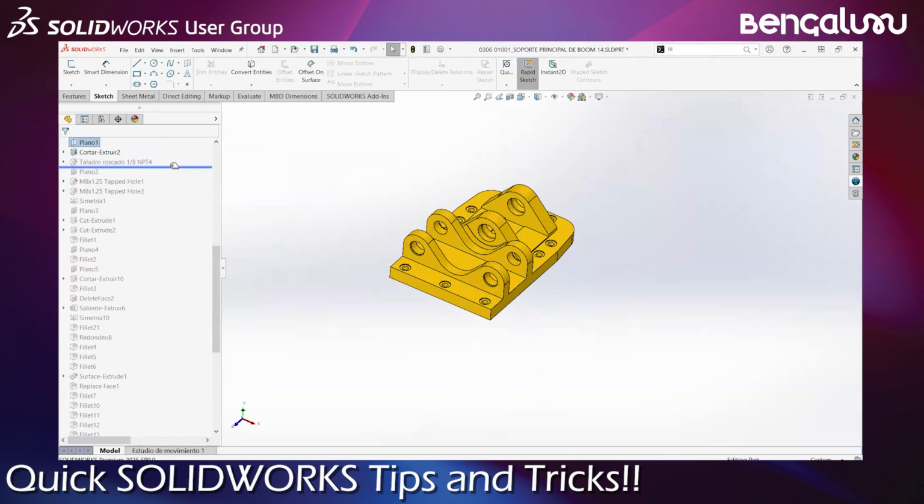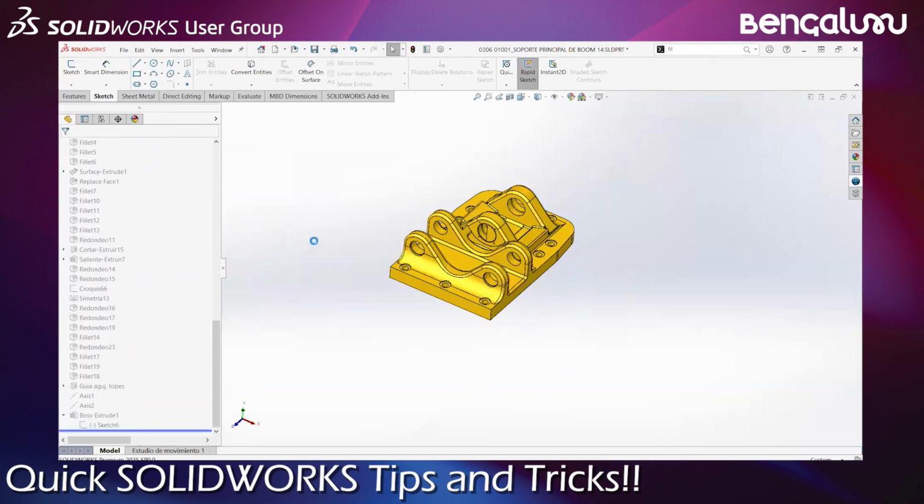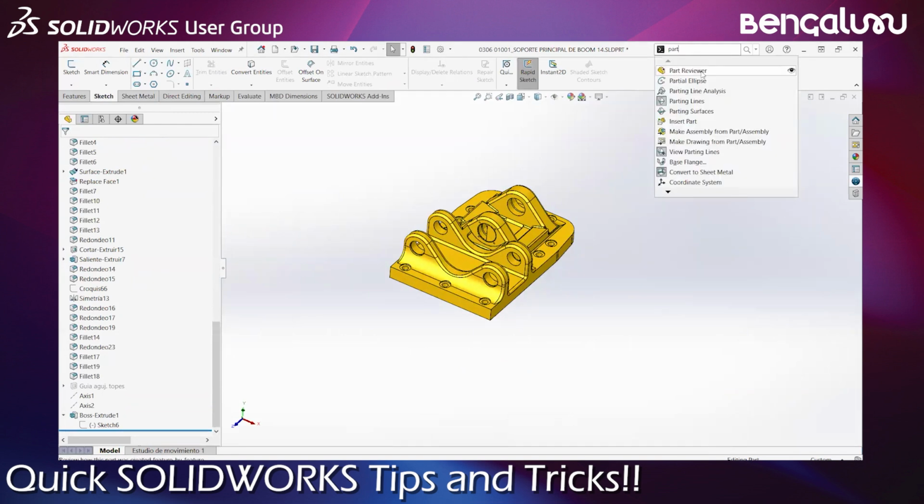So what has he done? What is the first step? What is the second step? This is how generally step by step review is done for each of the or most of the drawings, right? But a better way in SolidWorks is, let me put it back where it was. So you can actually search in the command for something called part reviewer. Okay, we have this part reviewer.